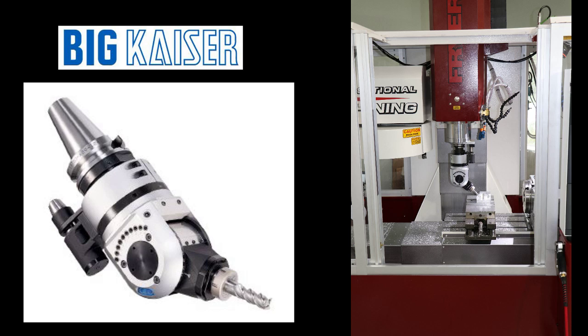So fundamentally, I can take a simple 3-axis machine tool like we see here today and convert it into a basic 5-axis kinematic. Now, the other two rotaries are obviously manual, so I would have to adjust them as I want to use them, but I can, for all intents and purposes, make this into a low cost effective 5-axis machine tool.